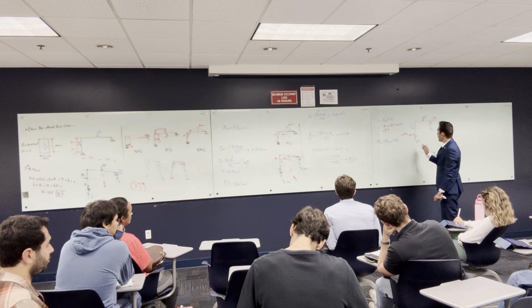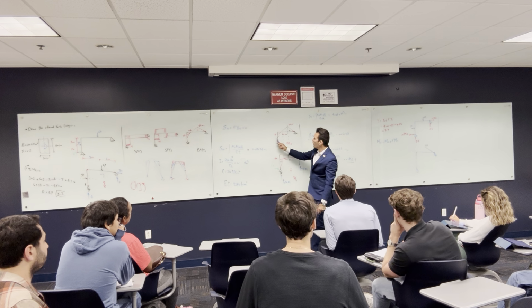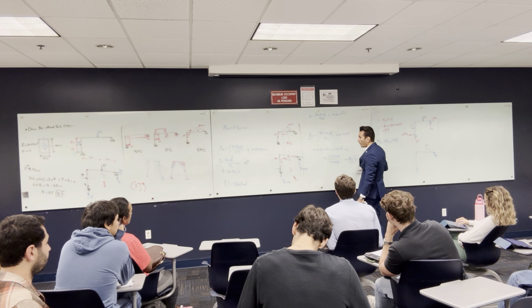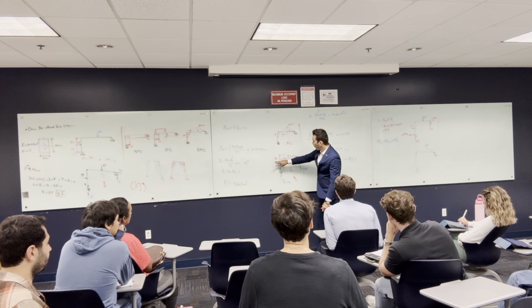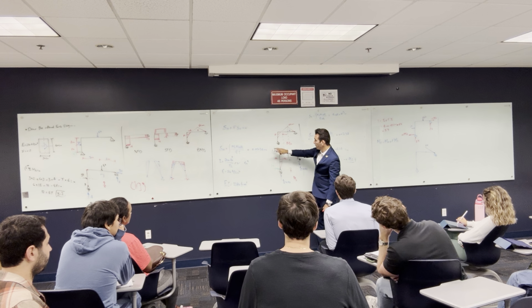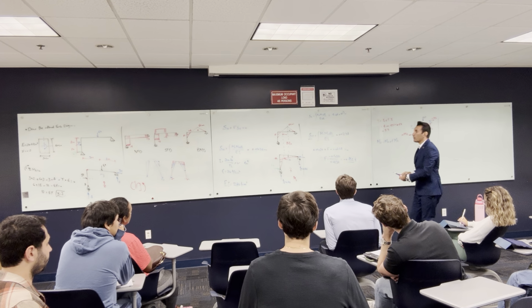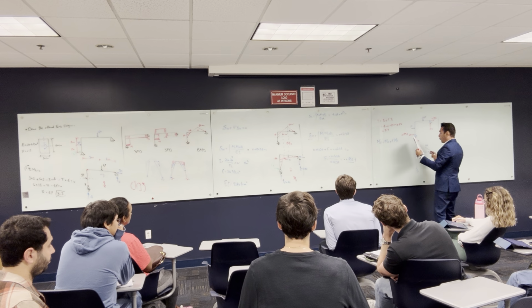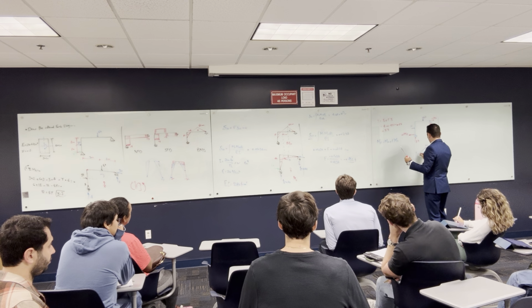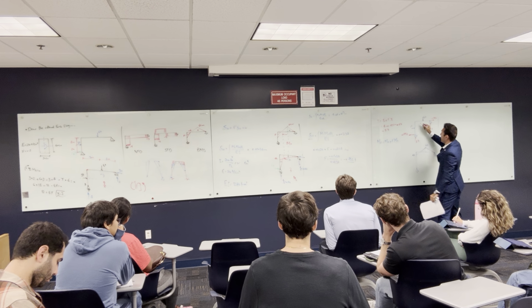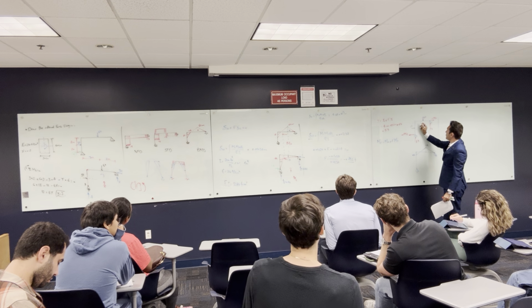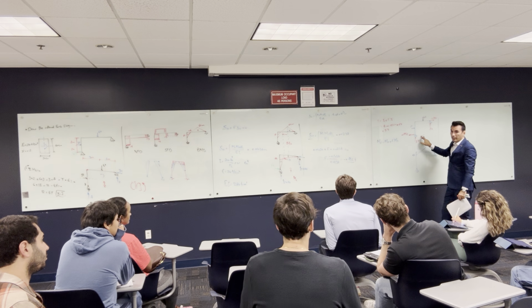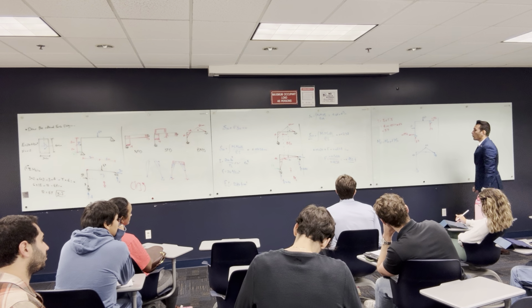And then you get the value of the moment here. You can do the same thing here. The value of the moment is 6, and it's negative, minus 0.45 multiplied by -4, so it's going to give you positive. This is negative plus positive, so I can imagine that the 6 is going to go less than 6, so it's going to be 4.2. So this became 4.2. Or actually you can get the moment here by 2.3 multiplied by 6 positive minus 6 multiplied by 3 negative, and you find the value is going to be equal to 4.2.